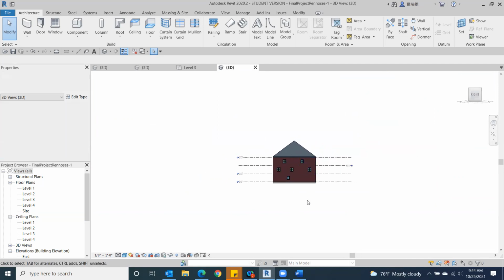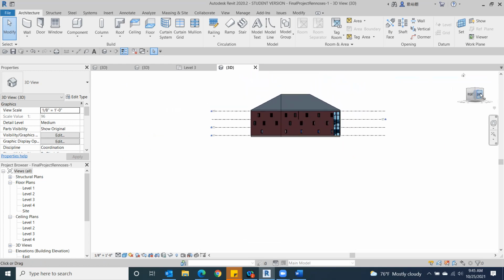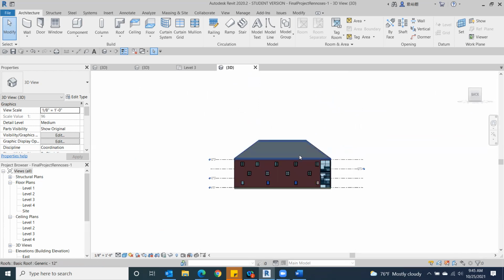Sometimes when we're looking at our floor plans, we want to get our windows lined up exactly so they're even within the room itself. But we always have to remember that it's going to be reflected on the outside of the building and how that looks. So it's a fine dance on how to incorporate our interior and exterior windows. So these are an easy fix. You can go back, but it's another thing that we think about when we're creating our buildings.